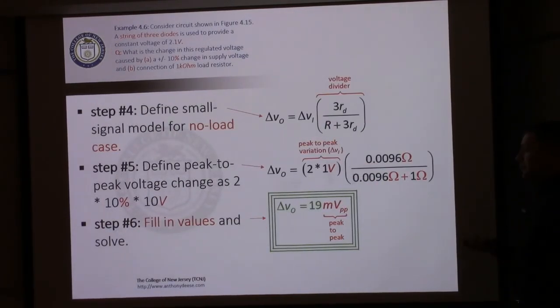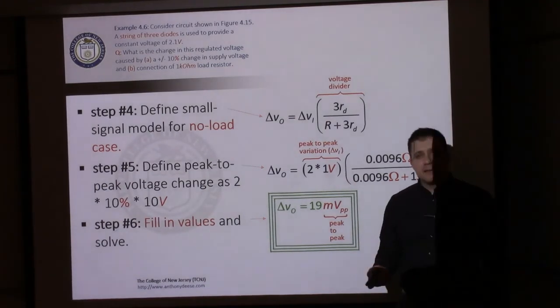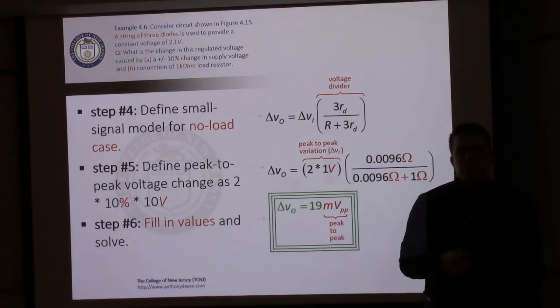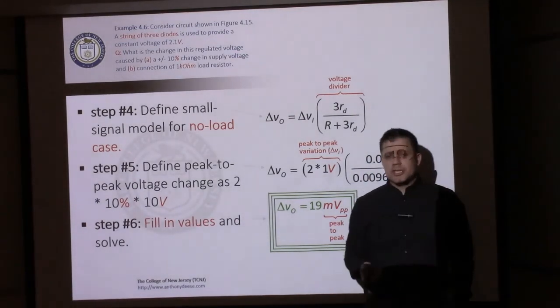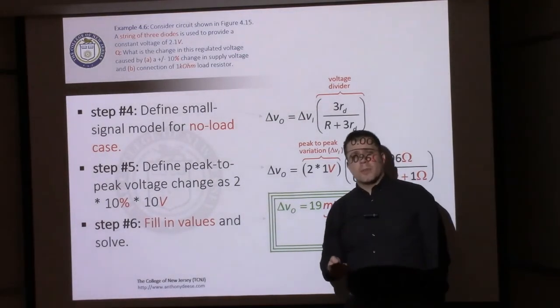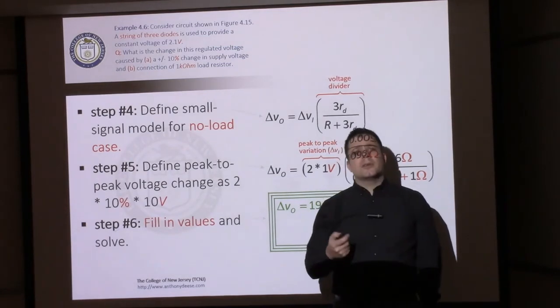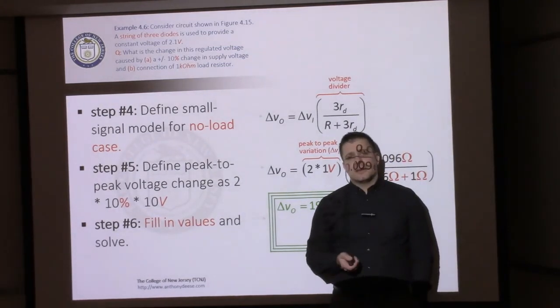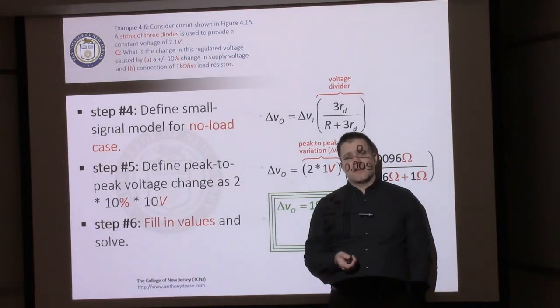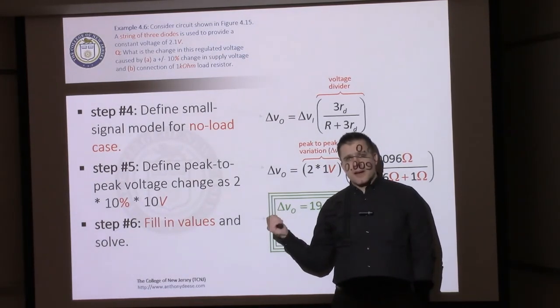millivolts. So the question that I ask after that is, and we kind of forgot to do this with the previous example, we need to check whether we're satisfying our condition for using the small signal model, which is essentially that the amplitude of the ripple across the diode has to be less than 5 millivolts. So is that satisfied here?